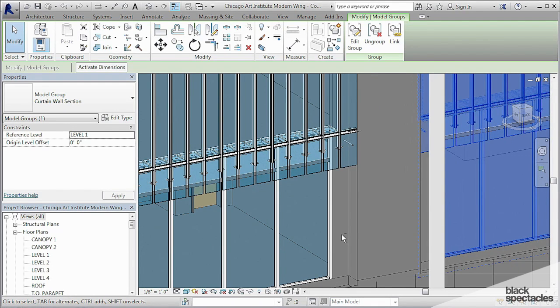these things out ahead of time, and usually when I create a complicated curtain panel like this, I will sketch everything out by hand. I will sketch with a pencil or a pen. I will sketch out the elevation of the panel, and I will sketch out the plan of the panel, and I will draw all the dimensions in the sketch, what I think they need to be, before I actually go into Revit. Because if you go into Revit not knowing what you're doing and just randomly start building stuff, it's going to be a disaster.